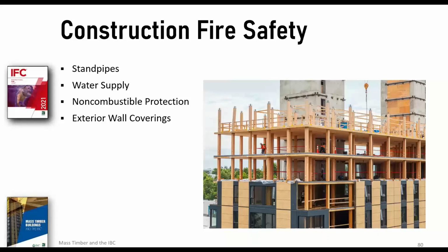Some of the provisions apply to all construction, and some apply just to mass timber. I will distinguish which ones are which as we go through it. But the construction fire safety provisions put in by the TWB were standpipe requirements, water supply, and non-combustible protection during construction. Paul talked about the finished product. I'm going to talk about the requirements during construction and exterior wall coverings.